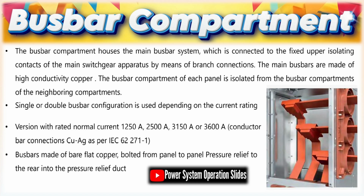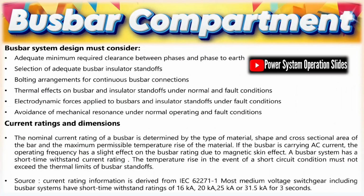Percentage differential relay. Uses operating and restraining coils to avoid false tripping during external faults or inrush. Trips only when differential current exceeds a percentage of through current. Enhances stability and sensitivity.